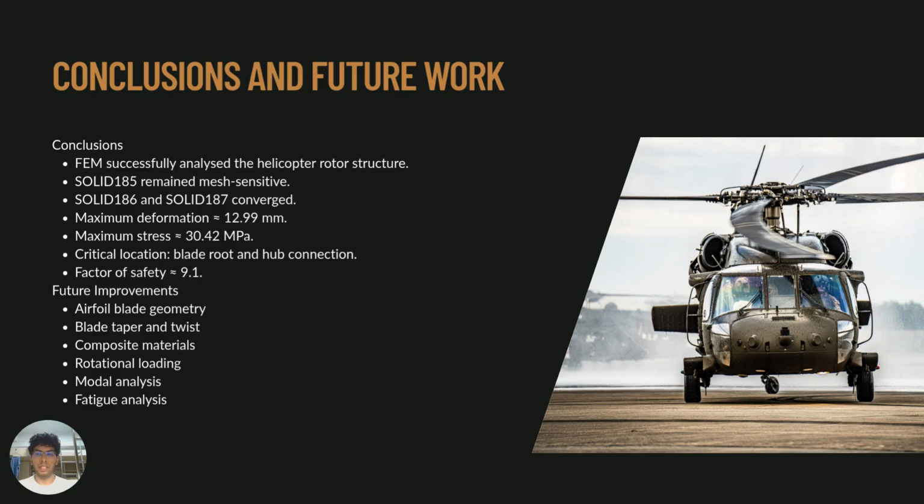The maximum deformation obtained was approximately 12.99 millimeters, and the maximum von Mises stress was approximately 30.42 megapascal. The critical structural region was identified as the blade root and hub connection. Using the material yield strength of 276 megapascal, the calculated factor of safety is approximately 9.1, indicating that the structure remains well below the yield limit under the applied loading conditions.